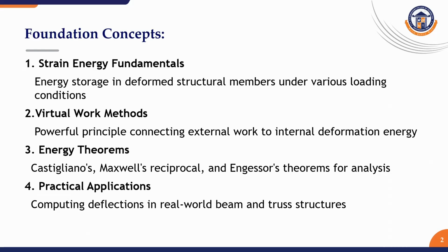Foundation concepts. This lecture is built on four foundation concepts. First, strain energy fundamentals, in which how energy is stored when a member is deformed will be discussed. Second, virtual work methods, which connect the external work to the internal deformations. Third, the energy theorems, such as Castigliano's and Maxwell's theorems, which are widely used in analysis. And finally, the practical applications of energy methods, especially calculating deflections in beams and trusses. Remember, whenever force methods become lengthy, energy methods simplify the problems.